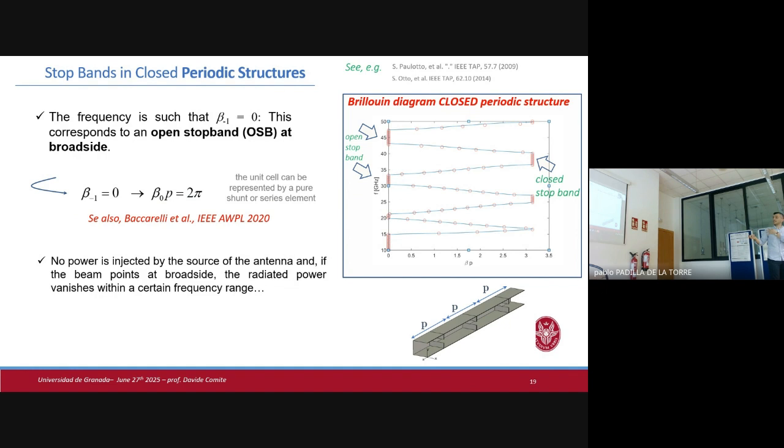And the idea was to develop radars. Radars have to manage a huge amount of power, so you cannot use a lens made of dielectric. Even today, when we need to manage high power, we use waveguides. So this one is a periodic structure. You load the fundamental mode of this guide, which can be TE10, as you well know, or TE01, depending on the orientation.